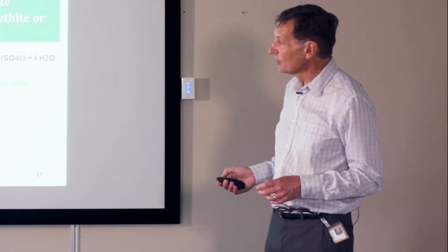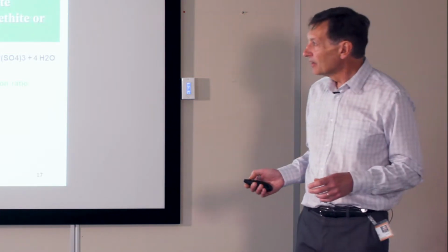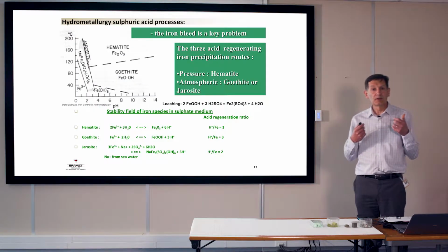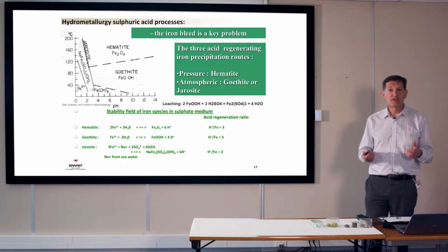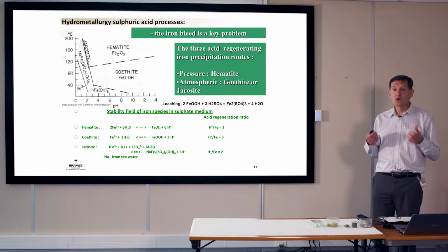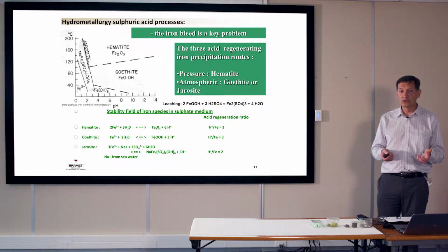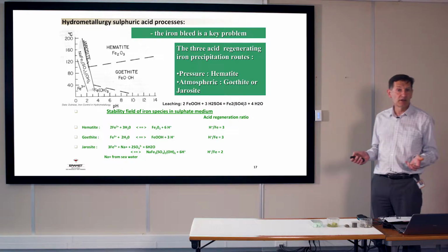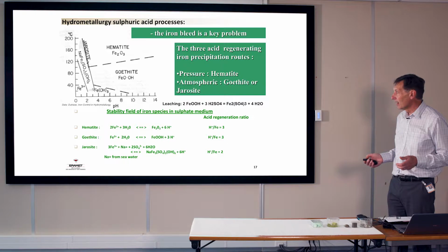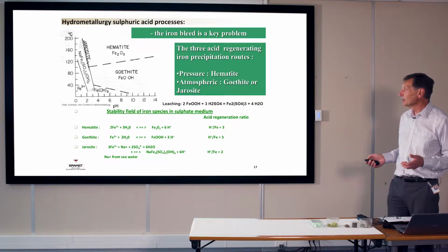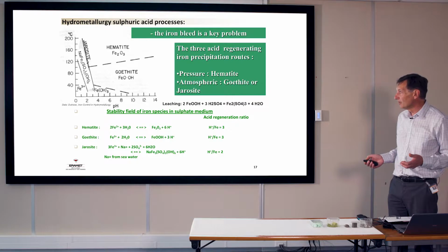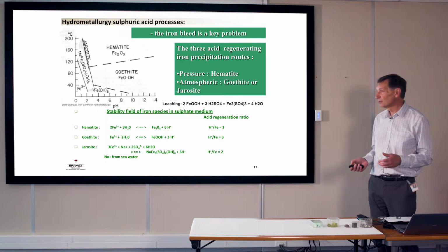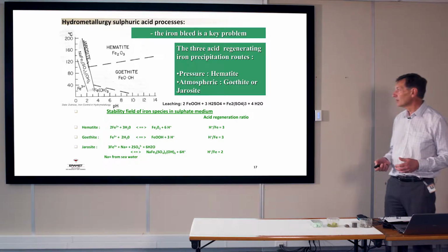Why is this kind of diagram very important? Because at high acidity or high pressure, the leaching conditions are very drastic, and it's a way to dissolve all the nickel well and get a very high yield of nickel recovery in the solution. At rather smooth operating parameters, you precipitate goethite, but you will decrease the iron recovery of such processes, and you will see the results in the presentation.